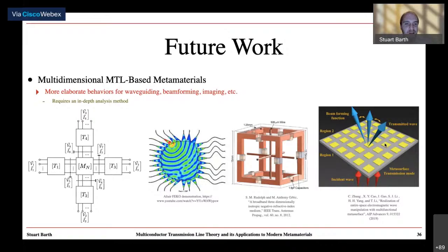So some ideas from this are the analysis of multi-dimensional or multi-port networks shown on the left. Beside it, I've shown this Rotman lens, which are very electrically large structures for signal routing applications. But this could be imbued with a metamaterial and miniaturized a significant amount if we knew how to properly control the waves propagating through the structure.